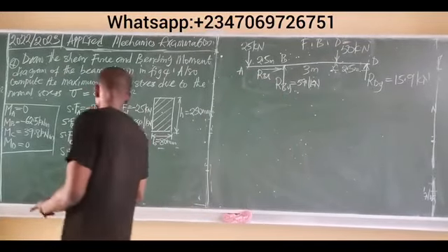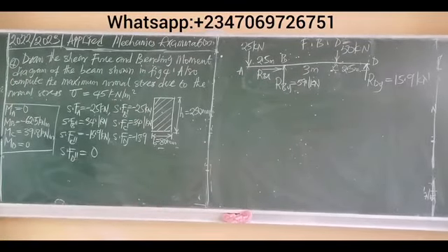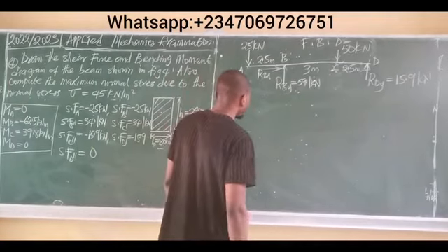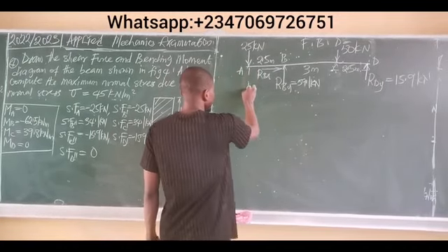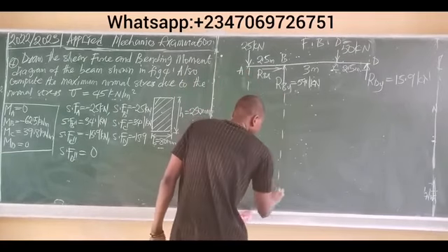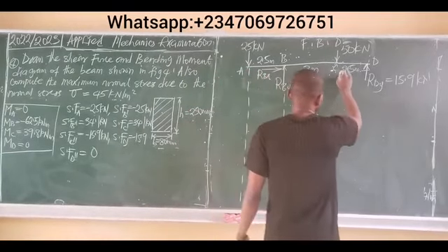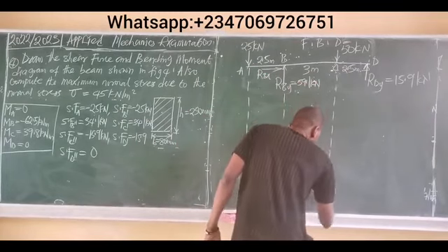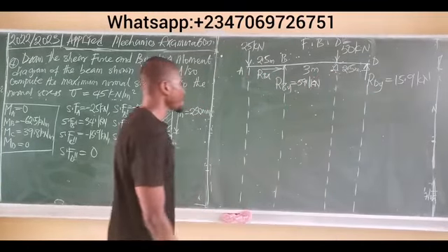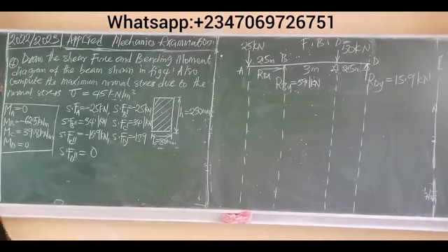All right, guys. So these are the values of the bending moment analysis, and these are the values of the shear force analysis. So let's plot the diagrams. To start plotting the diagrams, first thing to do is trace out all the points with broken lines. Trace out point A, point B, point C, all the points with broken lines. Now let's start with the shear force diagram.